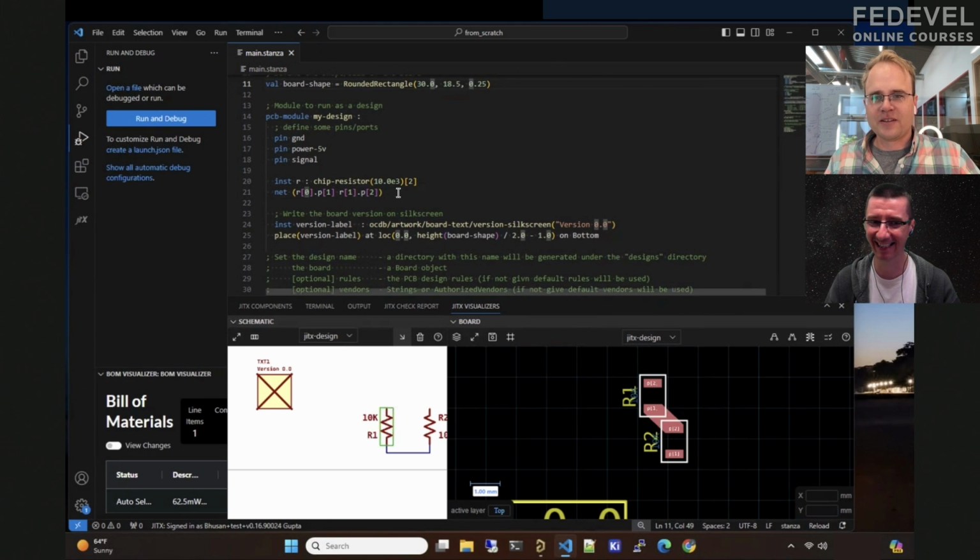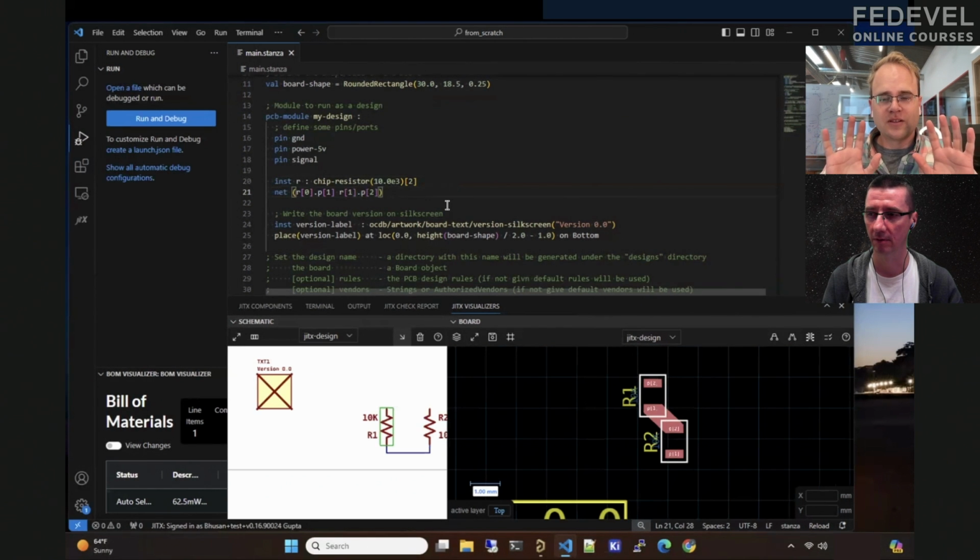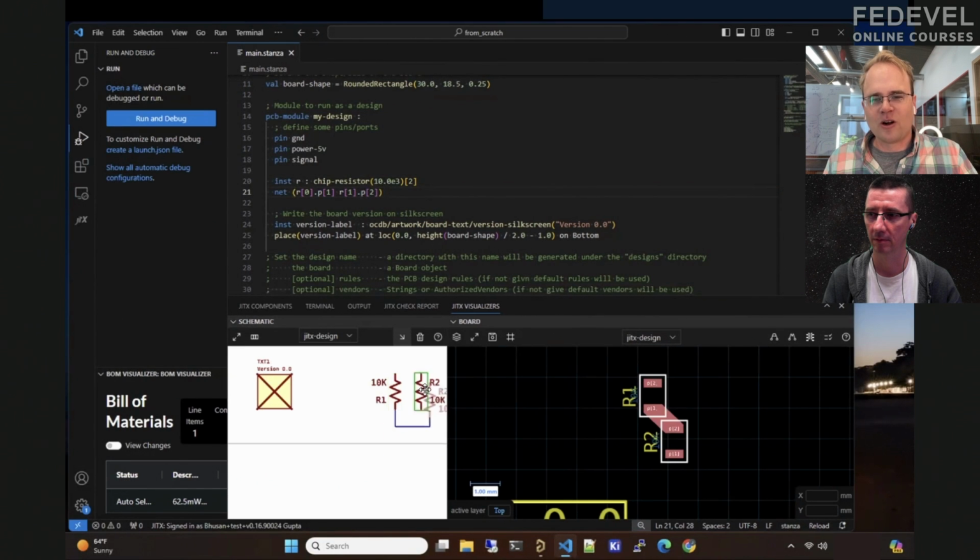All right, so they're connected there. This is interesting. We didn't draw the schematic, and it just... Yeah, but it's still nice to have a schematic. A lot of people really like it when you're working with code. I'm a very visual person myself. So this is my common mode of working. I'll edit the code, and then I'll see the schematic and the board updating. So I'm still working with the views that I'm used to, but I'm driving it all from code, because you can't draw something wrong and make an incorrect net. So you get all the correctness from code, but you still have that visual.